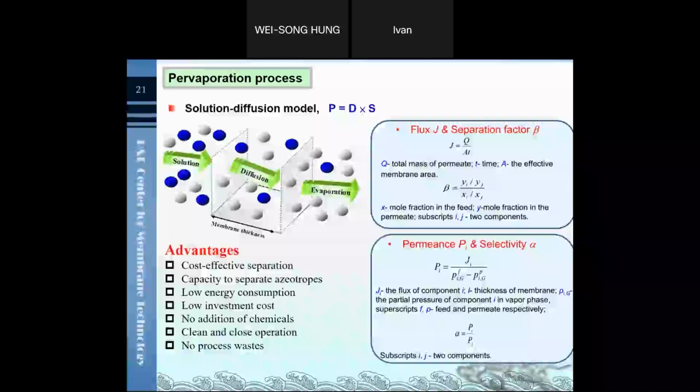So this one is talking about the pervaporation, which follows the solution-diffusion model. The feed solvent will first be dissolved on the membrane, and then diffuse in the membrane. Finally, they will be desorbed at the other end of the membrane.